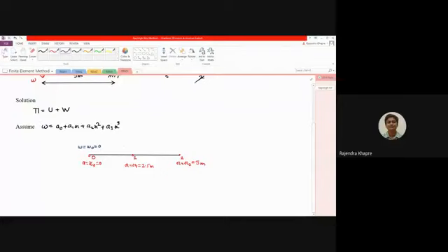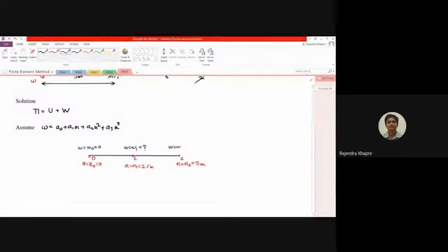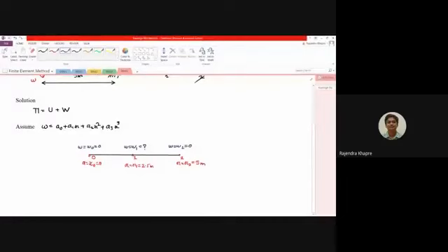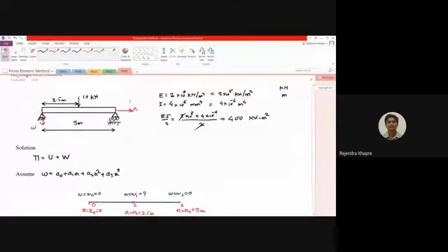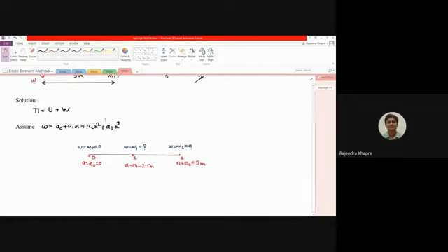Similarly here the w will be called w1, and I don't know the value of w1, because the load is there, so depending on the quantity of the load, the value of w is going to change. Now at point number 2, w will be called w2 and its numerical value will be 0, because at the second point a roller support is there, and this roller support does not allow displacement in the vertical direction, that is in the w direction. So this is one boundary condition which is available over here.